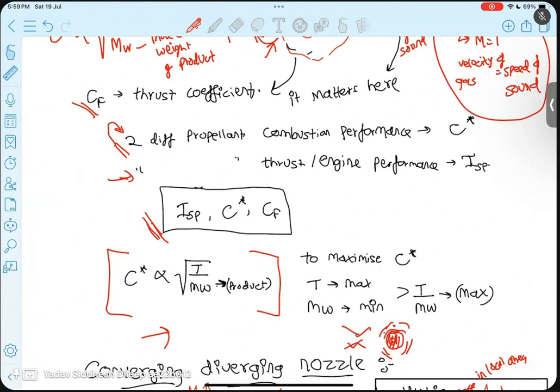Yeah, I got your question. So I will explain. This is a hypothetical case. If your combustion is going on, you have the thermal energy stored, and when you convert all the thermal energy and give it to the gases in the form of kinetic energy, your gases will be accelerated to some velocity without any nozzle. All the thermal energy is given to the gases, the gases are in space, vacuum, and they are accelerated to a maximum velocity that is called the characteristic velocity.